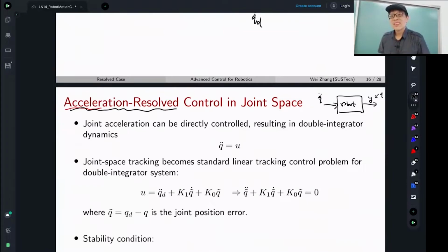Liu Ben? Typically, if you want to control a robot, the interface is joint velocity, or even position. You don't directly control the acceleration, but this is a model. It is a good interface for generating motion control with torque as input. So let's assume you can directly specify it.